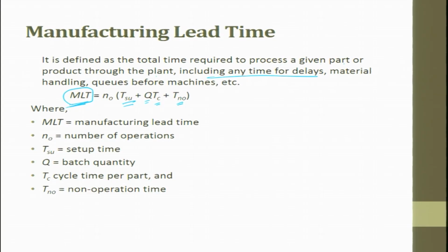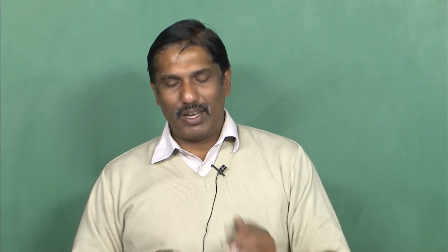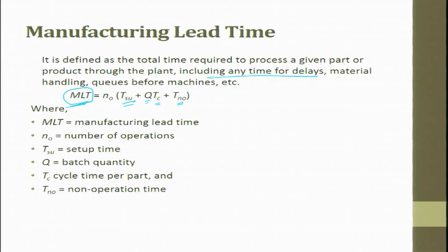Manufacturing operations are a set of operations. The order is released, please produce that part. The part gets into the first machine, keeps undergoing all the operations and gets out. The time by which it gets out so that a customer could capture it is called the manufacturing lead time. You have customer lead time and you have manufacturing lead time. These are two different things.